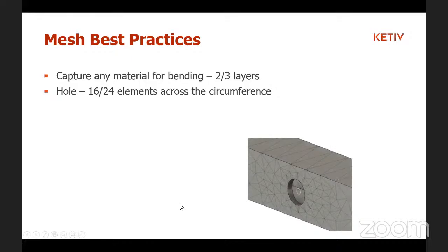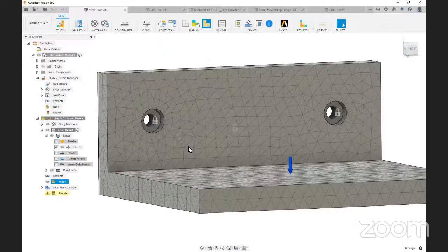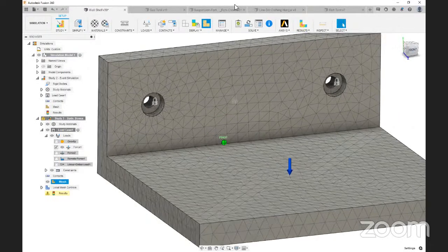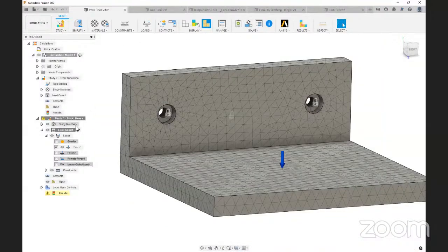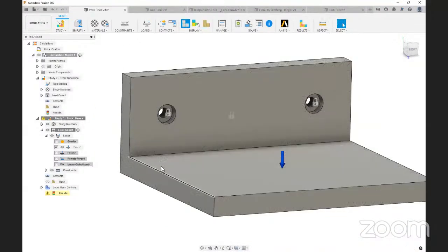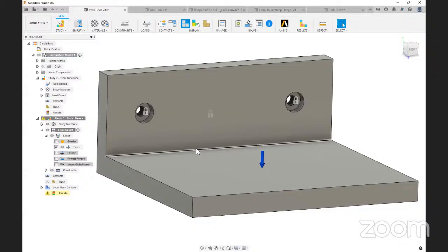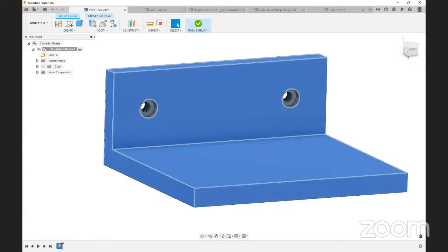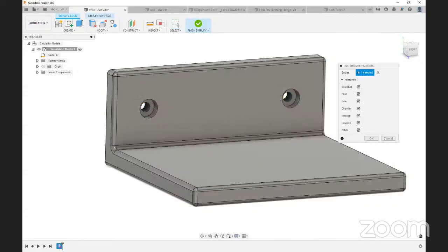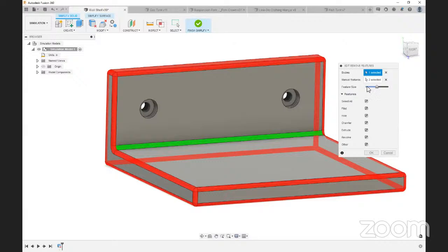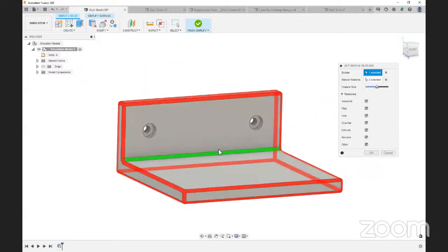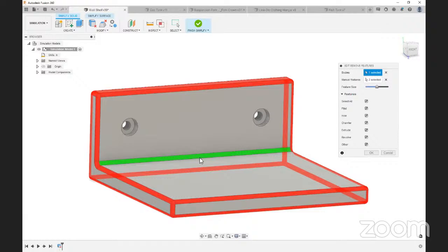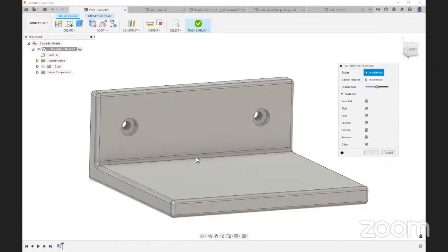So there's an image example. Leaving fillets where it matters. All right. So as you saw earlier in this example, let's go back to non-mesh. Okay, so we don't have any fillets here at all, but we actually should, because remember when there's a lot of stress there and we simplified this and we took out this green line there. We actually want to leave that in. That's because it's actually really critical to the overall end result of this, as you may guess.